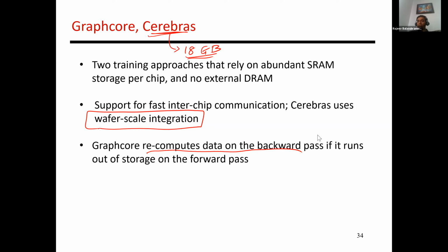There are some other formats also in the mix. So I know that folks at Intel had a paper on something called FlexPoint, where they're looking for locality in the data and changing the number of bits used for exponent and for the mantissa. So there are a few different formats, but I think the general consensus is that 16 bits should be enough.